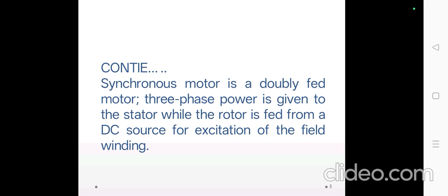Such a device which converts electrical energy into mechanical energy running at synchronous speed is called a synchronous motor. Synchronous motor works on the synchronous speed and cannot work at any speed other than the synchronous speed. The speed is constant irrespective of load. Next one is rotating magnetic field. Rotating magnetic field can be defined as the field or flux having constant amplitude but whose axis is continuously rotating in a plane with a certain speed.